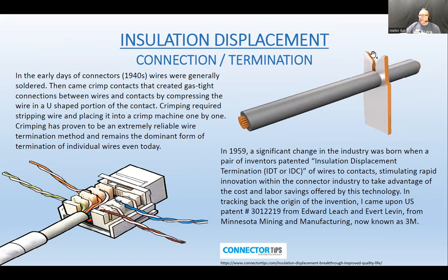If you push that into this type of connector that is kind of spring-loaded inwards, and you shove that in with some physical power, that connector is going to bite into the insulation and make connection with the copper wire that is inside. So that's why it's called insulation displacement connection. Much faster than soldering and quite reliable.